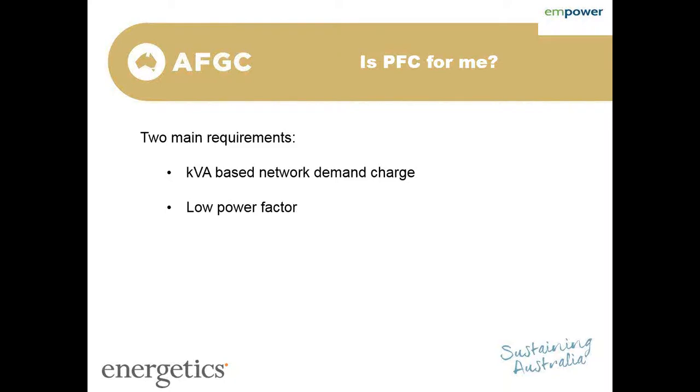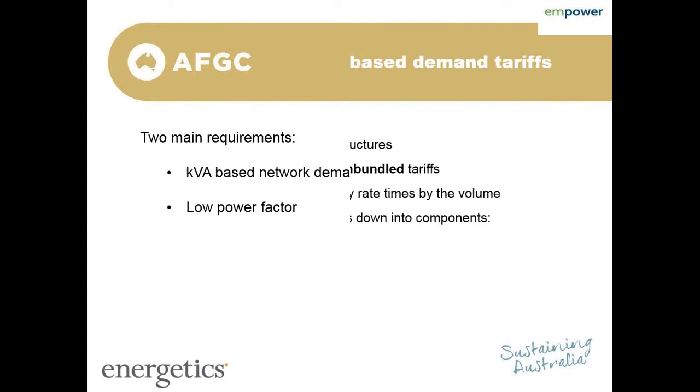To reduce power and, yeah, save some money. And I'll mention just briefly as well, something else you should be looking at is whether you have a lot of variable speed drives on site. That's something that can influence whether implementing power factor correction can sometimes play havoc with variable speed drives, if you have a lot of them on site, just by the way they operate. So that's something to consider there. It's not necessarily a deal breaker for them, but something to factor into your considerations.